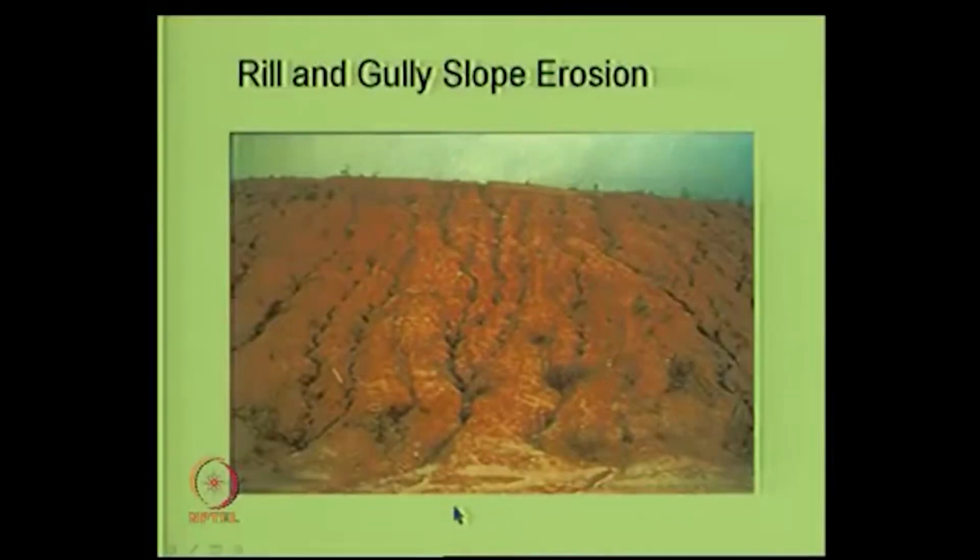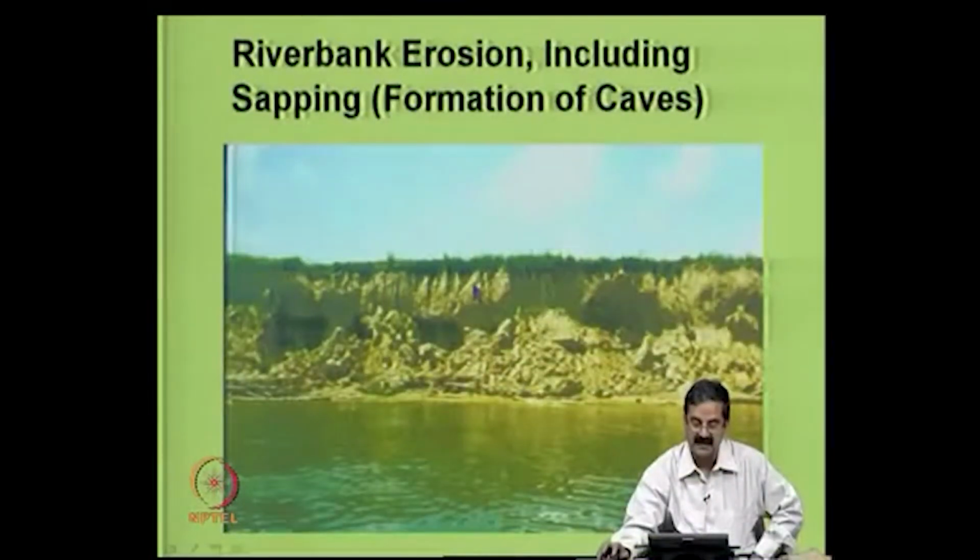So, this is a typical diagram of how erosion could be manifested. For example, we call this rill and gully erosion. These are quite common in India and many other places. That is because of the rainfall infiltration and the inability of the soil particles to withstand the drag forces. The drag forces are exerted onto these soil particles, and they form erosion gullies. This is another classical example, seen in many places along the rivers, and the possibility is that if you continue like this, the whole river course could change, the nearby water supply to the villages could get affected, and everything. It's a very risky thing.